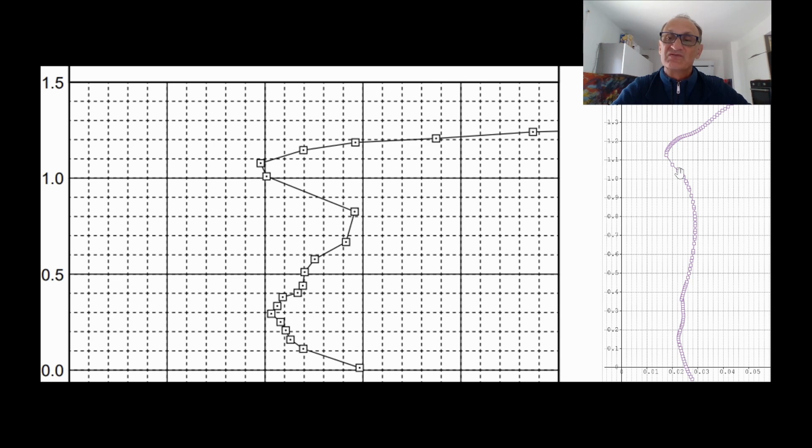It's almost the same value, and all along the curve, especially from 0.5 lift to the maximum, because it's unlikely that you are working at 30 meters per second with flap deployed at 10 degrees. It makes no real sense. If we look closely, the drag is slightly underestimated, but not so much, and everything looks good.